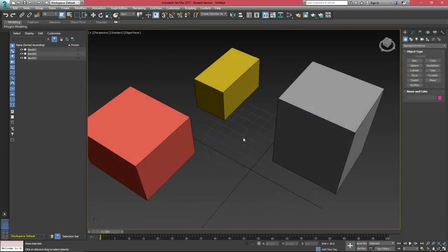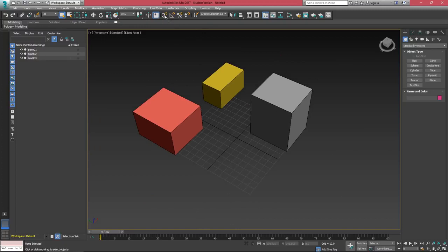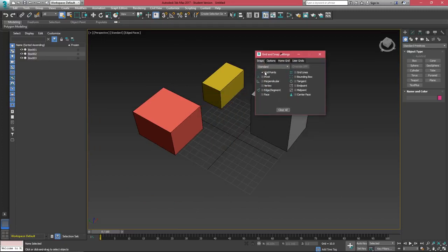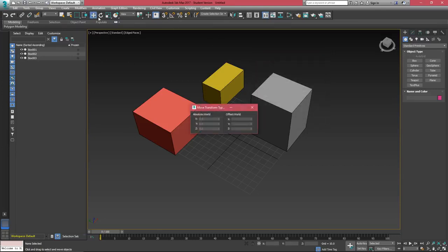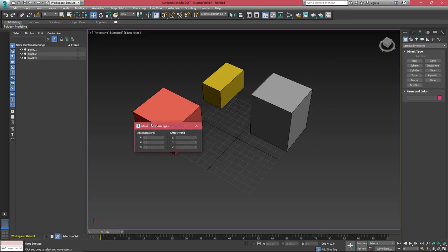A very helpful tool when you're working inside of 3ds Max is the snaps. There are 4 different kinds of snaps when working in 3ds Max: the movement, angular, percent, which is essentially just scaling, and then our spinner snaps. Most of these tools up top, you can right click on them to get an expanded dialog, which will give you more control over whatever option that is. The same works for our rotation and movement dialogues as well.